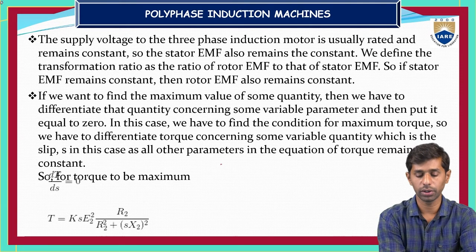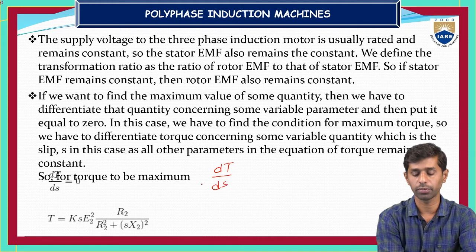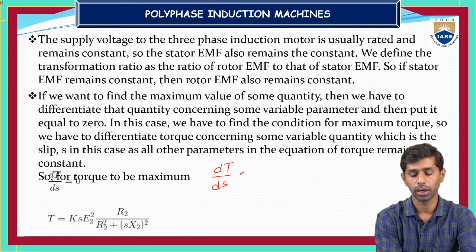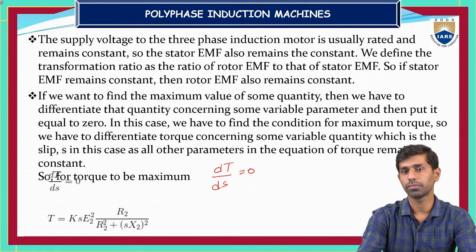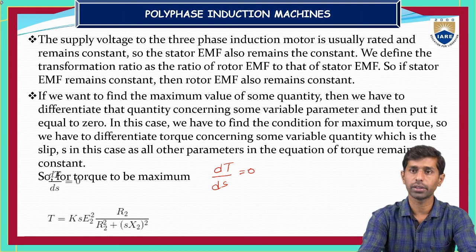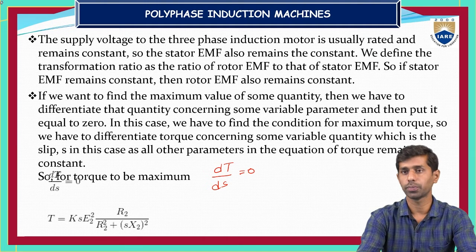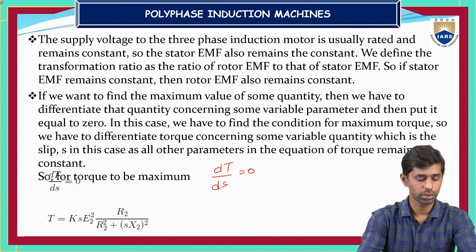That is why I am differentiating the torque expression with respect to the slip, that is dT by dS, and equating it to 0.